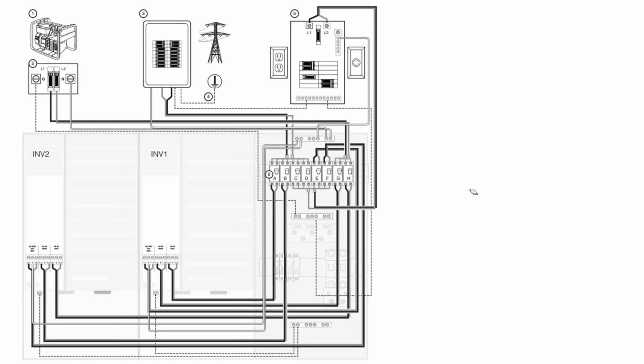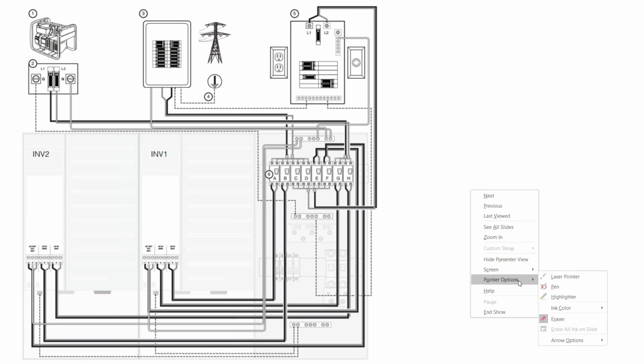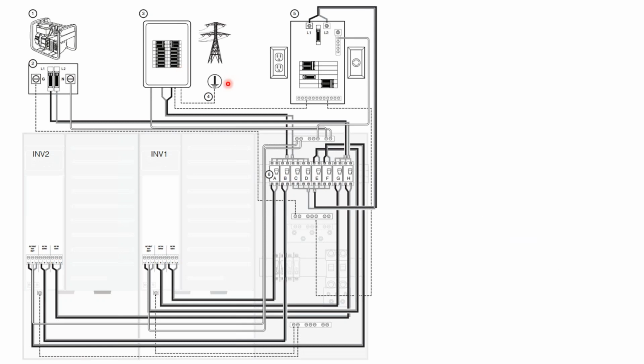And it's only supposed to be made at one point. In your electric meter, right where the power is coming into the property, you have a ground connection. Not on your side of the panel, but on the utility side, they're connecting the neutral to ground and establishing a zero voltage reference across the neutral, such that when that neutral starts to have more voltage in it than it's supposed to, it'll open up your breakers.